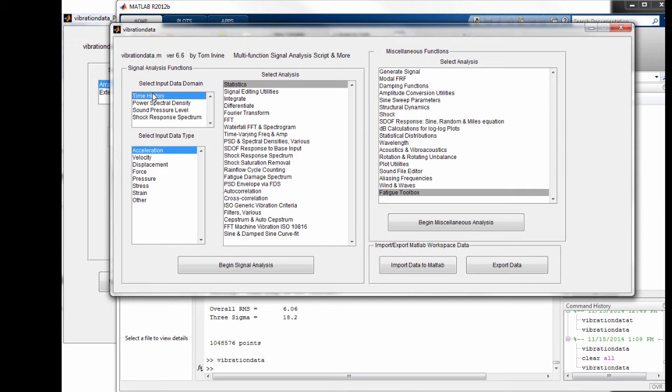Okay, so we've got a time history base input. It's an acceleration. Let's do a single degree of freedom response to a base input. Now, this is going to be the David O. Smallwood ramp invariant digital recursive filtering relationship. David Smallwood of Sandia Labs developed this formula. And this formula is so fantastically wonderful that not only does it work for shock, which was David Smallwood's original intention, but it also works for all sorts of long duration vibration as well.